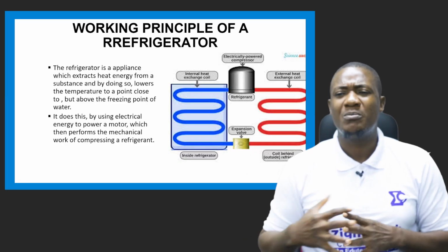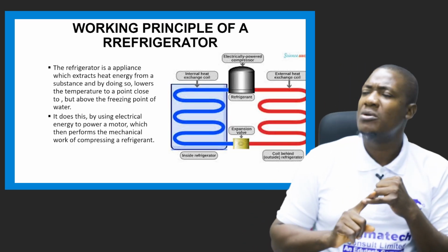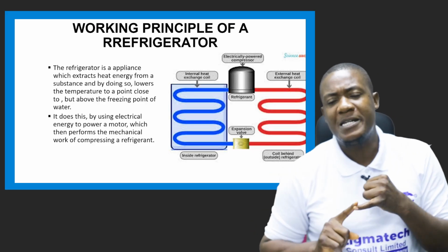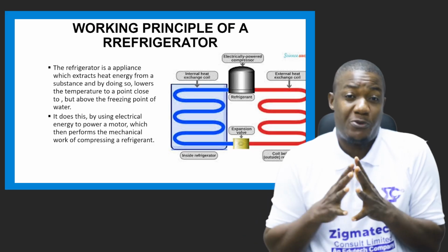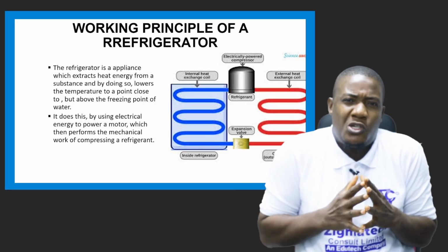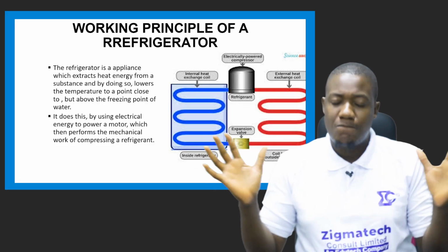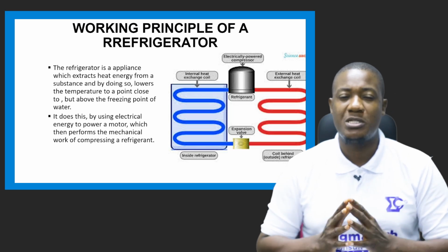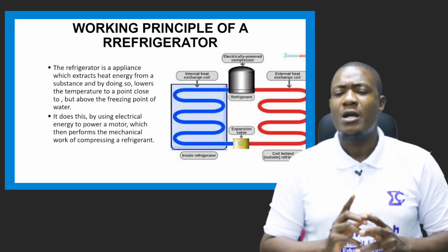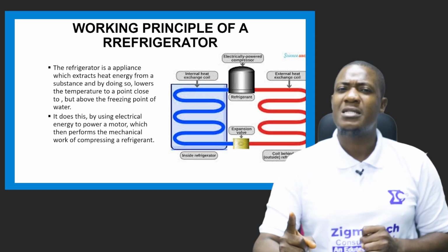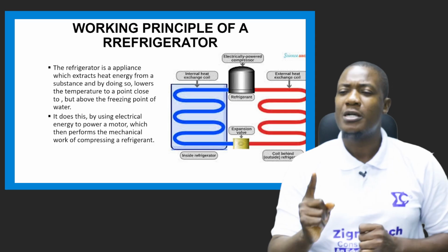Okay. Now, when that happens, the Freon in the expansion valve is expanded. Remember I said it's pumped at a high pressure, right? It's pressured. That's the compression. It's pressured into the expansion valve. Once it's in the expansion valve, the pressure reduces because the expansion valve increases the volume of the Freon, so to say. Now that the volume is increased, the pressure is reduced.